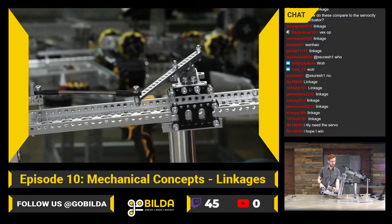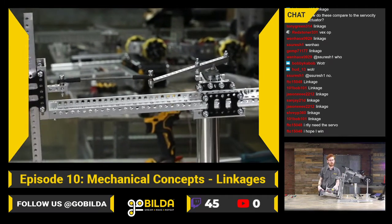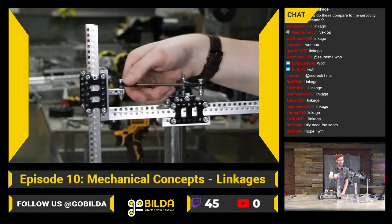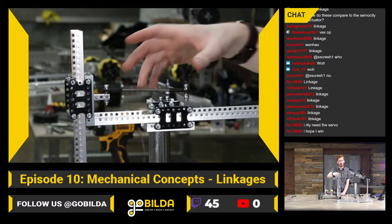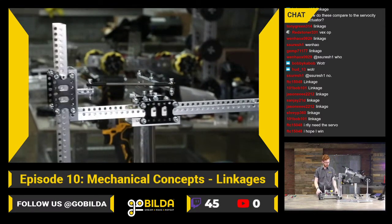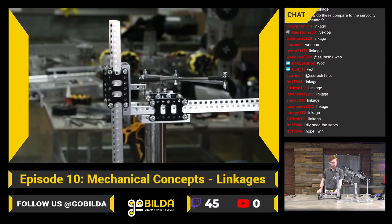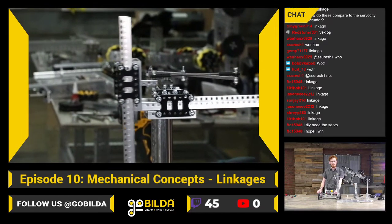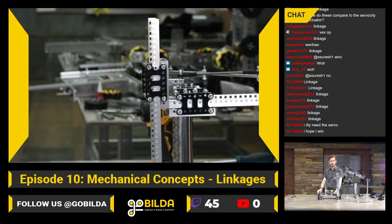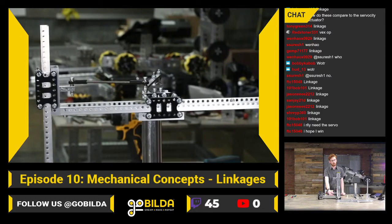The other big advantage of this setup right here is that it gives you a lot of customization about the length of this arm right here. You can rotate this half a turn and move that whole arm length by 0.35 millimeters, so almost nothing. That can be really, really helpful if you're trying to fine-tune exactly the amount of throw you get. The other thing about a linkage like this, where you're using rotational motion to create linear motion, is that your speed and force amount vary depending on where in your stroke you are.